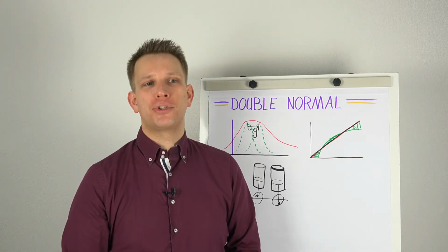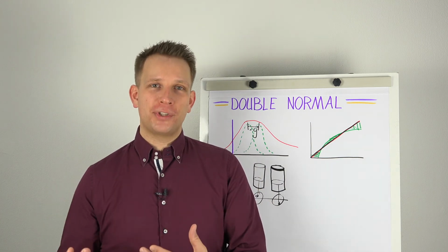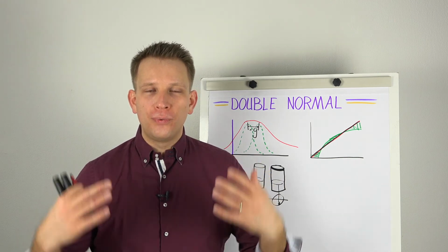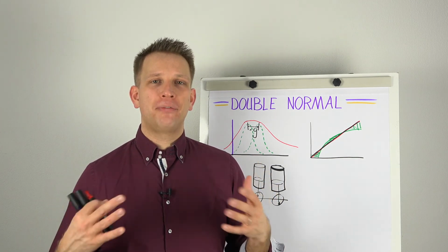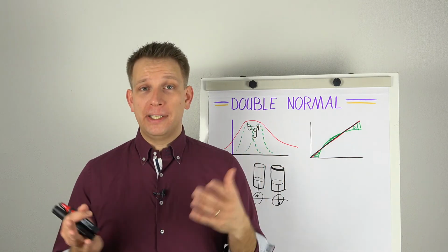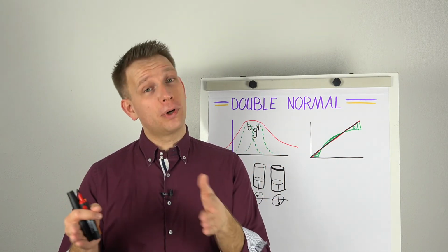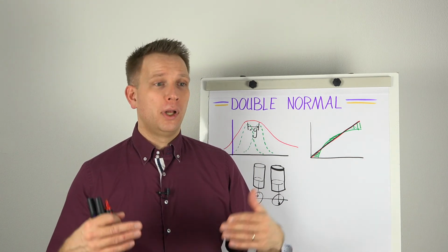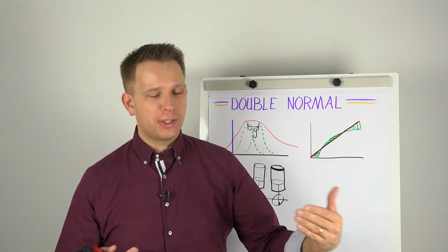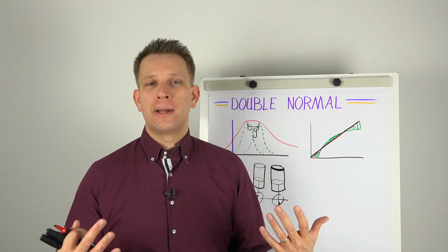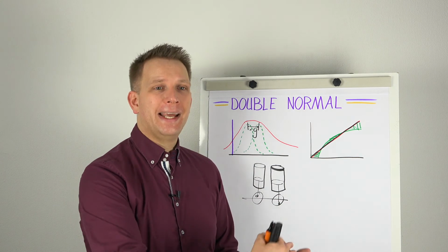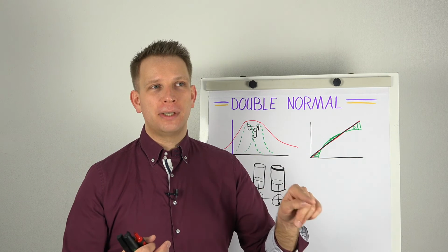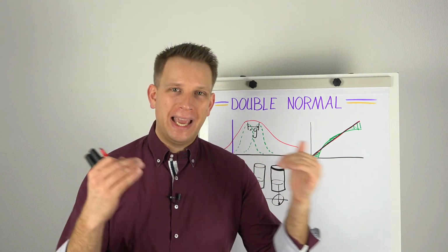although actually the underlying physics tell you to ignore, remove these data points. So look at your process, see what the physics are doing, what the real parameters of your process are, and if you see such things happening, like my two nozzles giving both quite a stable but separated weight of the product, or you see that a first or last slice is always a bit different, but it's still weighed, and then a check weigher throws it off the normal line, but you still have this data point, know that you have to ignore this data point.